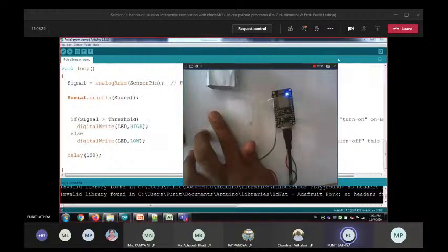So I will close the serial monitor window and I will open the serial plotter. If you can see this, you can see these beats per minute. That is the heart rate. Again, it is showing the number of samples, so the x-axis is not time right now. It is just the number of samples that you have taken.